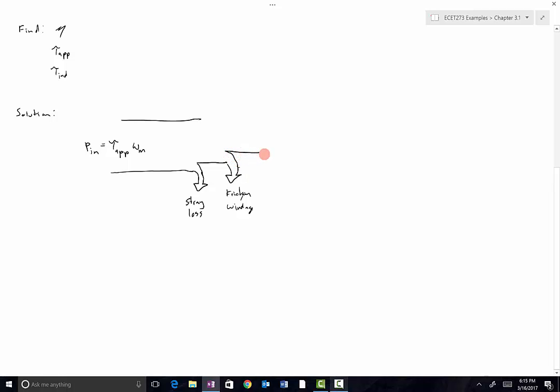Then we've got another loss mechanism inside the rotor called core losses, and this is basically the inability to totally create a magnetic field or loss in alignment of magnetic domains. So this is a loss in the magnetic core. And so those are the mechanisms of loss of converting input torque into a magnetic field that reaches the armature.